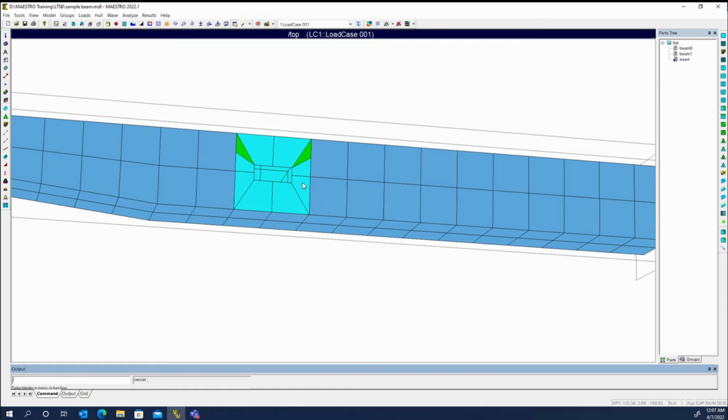So one thing you can do to adjust that is go into dynamic query and you can say flip pressure side. And that essentially changes the direction. You can see now with the arrows in the clockwise direction, if I flip pressure side, it's counterclockwise. So it's essentially changing the normal on that one element. So I'll flip it. And if I need to flip it back, I can after I do the split.